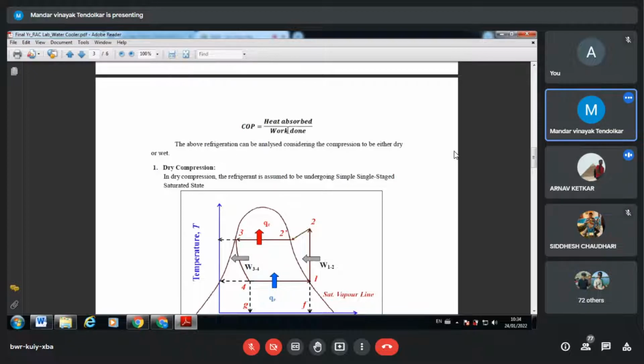Okay. So this covers my practical part. I will have a practical COP. Practical heat absorbed is equal to m Cp delta T of water. Practical heat rejected by water is equal to practical heat absorbed by the refrigerant, correct? So this will be related to the water part, m Cp delta T, which you can measure. You can measure m dot, Cp is constant, you can measure delta T with simple thermometers, correct? So this numerator part is done.